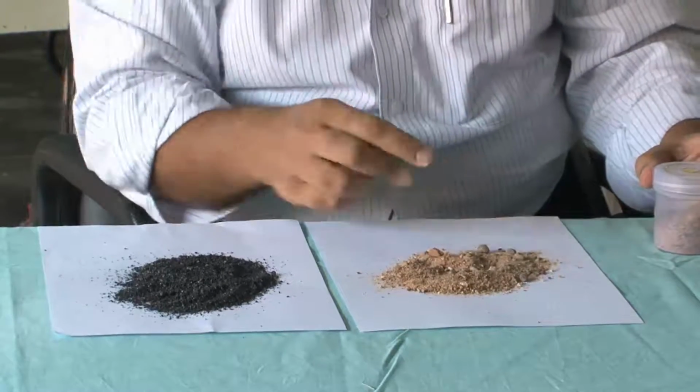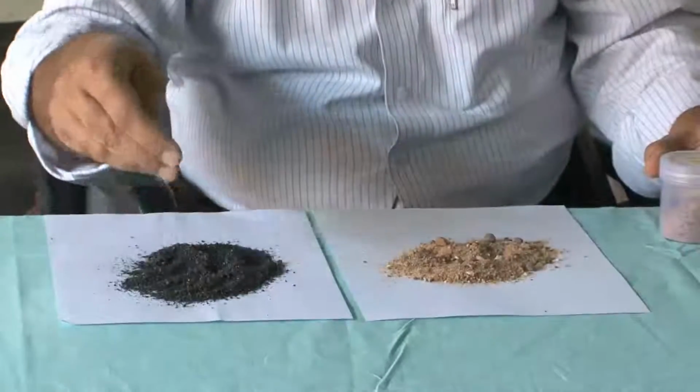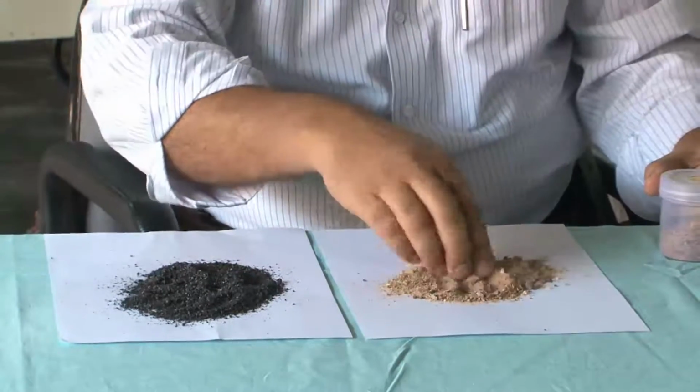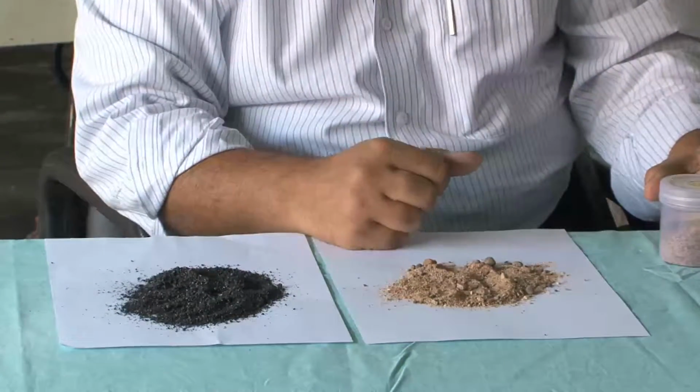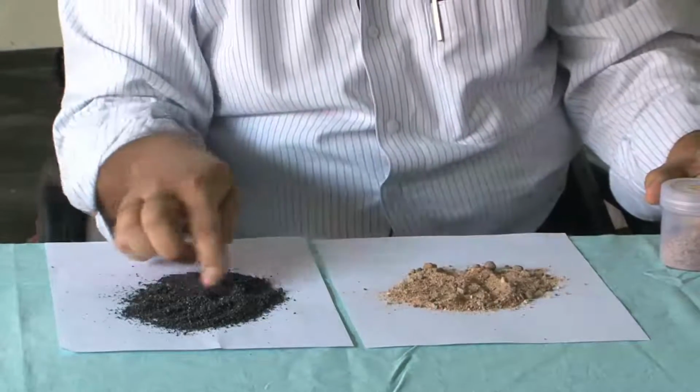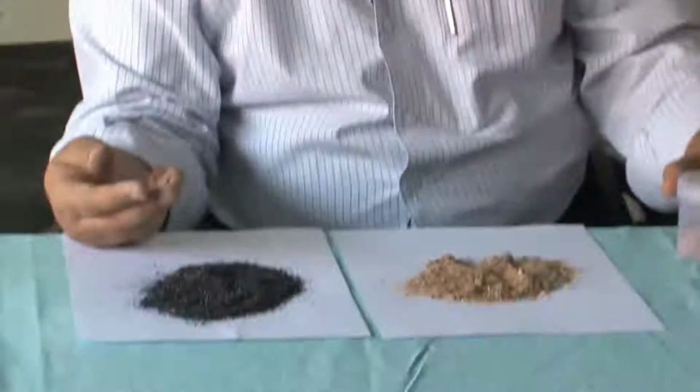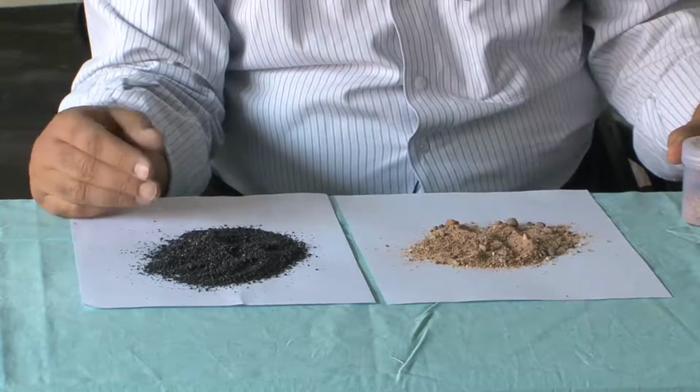There are differences, but there is a logical basis to believe that this material, copper slag, can be used as a substitute for normal sand, at least in concrete construction. Given the fineness of this material, it may not be possible to use it as a substitute for very fine sand. So, we have to go through the same tests as we go for normal sand, determination of fineness modulus, determination of water absorption and so on, and decide whether we can use copper slag or not, and how much of copper slag can be used without affecting the properties of concrete.